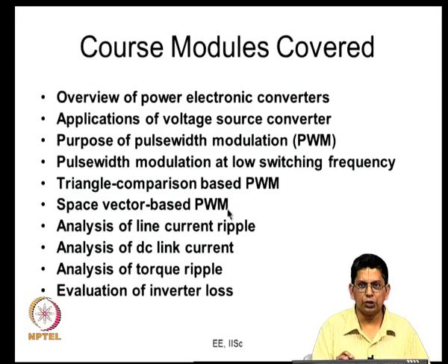We have also emphasized the continuous and discontinuous PWM methods, which are common to both the approaches, and the advanced bus clamping PWM, which comes under this space vector based PWM. All these have been emphasized reasonably well in this course up to this point of time.